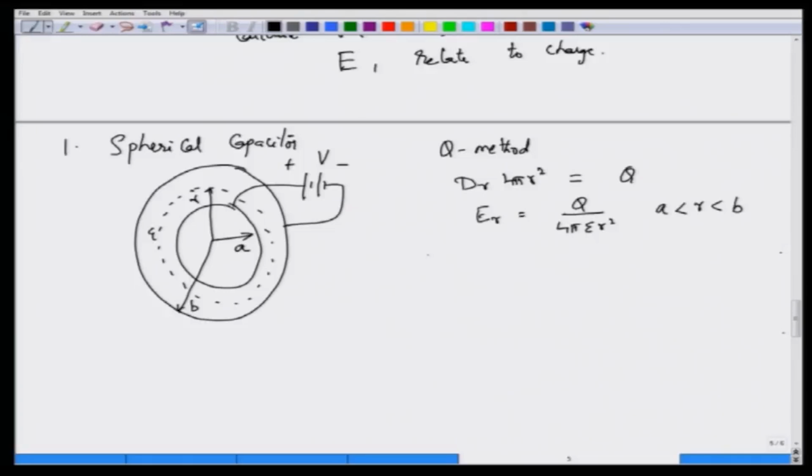Okay. What would be the potential difference? The potential difference would actually be the potential difference between the inner and the outer conductor, call this delta V, and we know that this is obtained as the line integral of E dot dl from 2 to, sorry, not 2 to 1, 2 here is B and this one is A, right, with a minus sign up here, or you could reverse the integral limits as well.